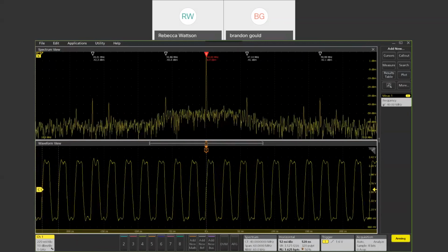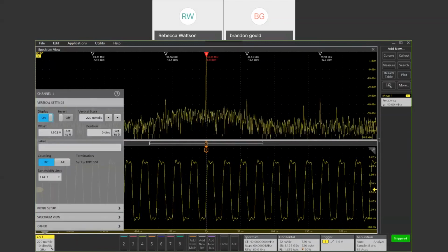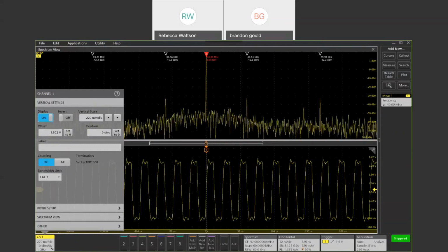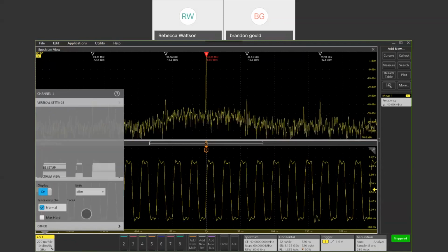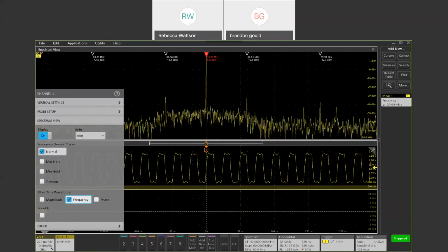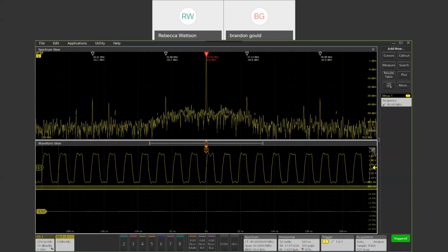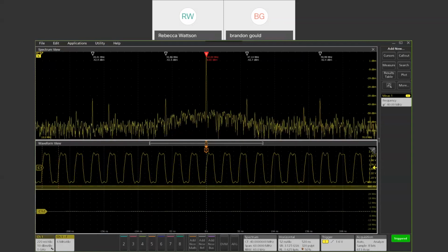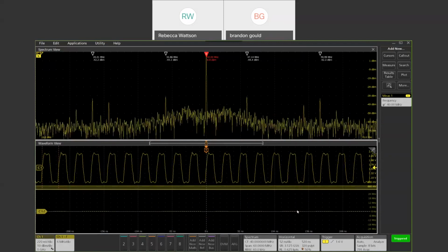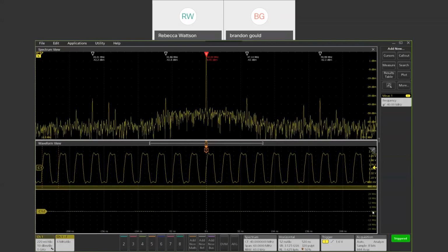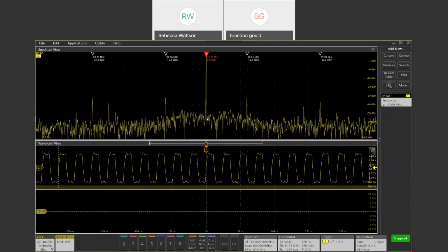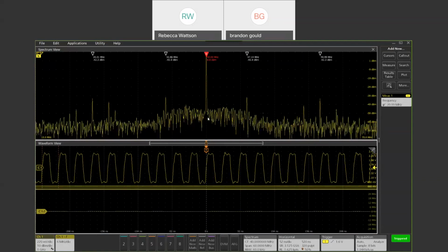And we're now going to turn on that frequency versus time trace that we had. It's the same setting that we used to see the triangular modulation of the spread spectrum clock. So one tap here and I have a frequency versus time signal showing in the bottom. Now, it may be a little bit difficult to see with the screen sharing, but there truly is a yellow line right here, which is showing me that there's about 0 hertz of delta from our center frequency, meaning this clock is behaving really, really well, it seems like, right?